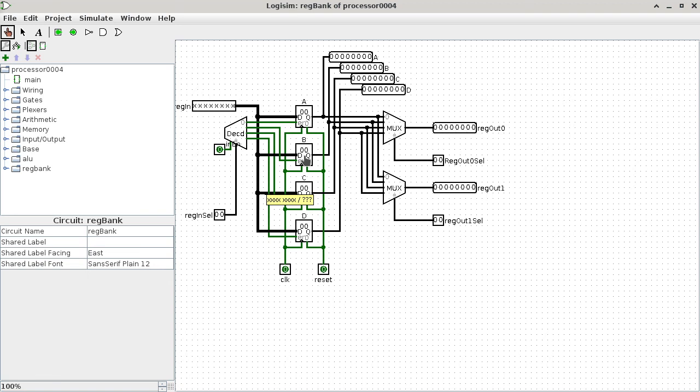Enable. When you have multiple things connected to the same input, the enable lets you say, okay, the rest of you just ignore this operation, but I'm talking to you. You are the one I want to remember what you're seeing in the D port. So that's what the EN pin is for. When you look at the EN pin, it is not hooked up together. It is single. Okay? They all go to the decoder.